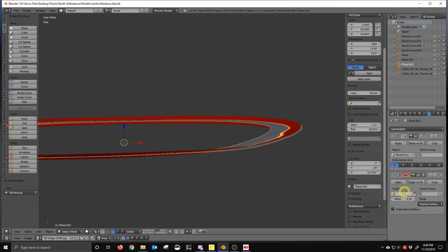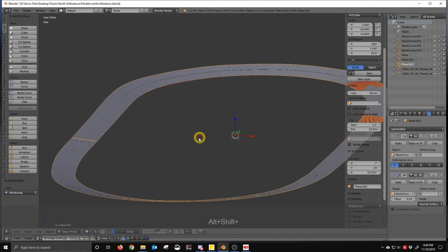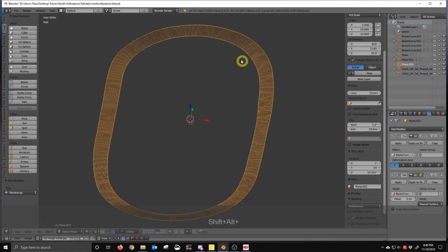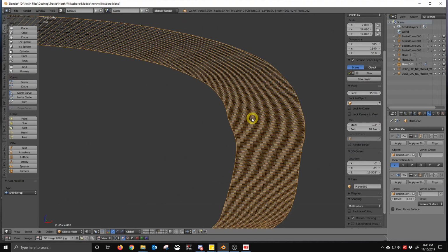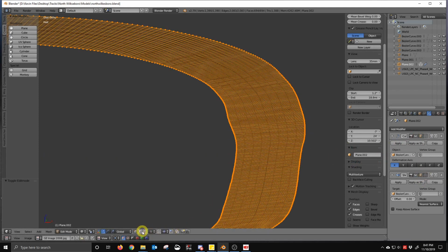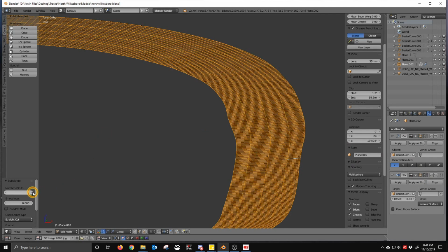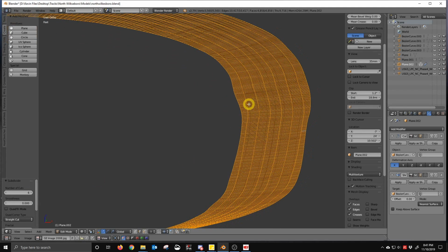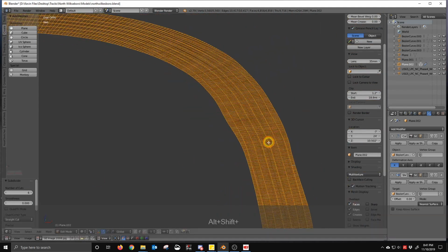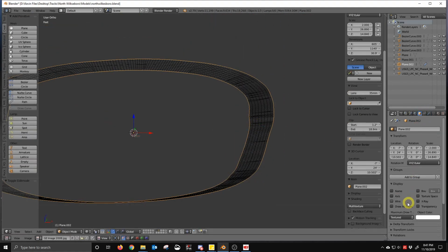So we want to add a shrink wrap, and then we hit the mesh we made from the data, and you can see it matches perfectly now. It took all those points that were outside and brought them in, so now it's a perfect match. You don't want it to be too wide, but just wide enough to cover every point of it. So obviously, just like before, just the edges now. Now we're going to take the center and subdivide a bunch of times, and that will be our cross section, and that will match our made mesh near perfectly.